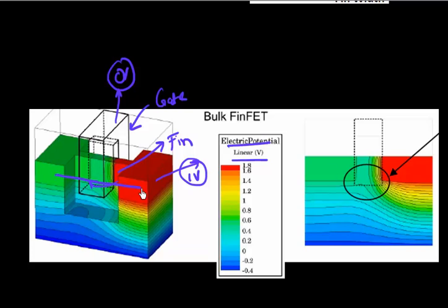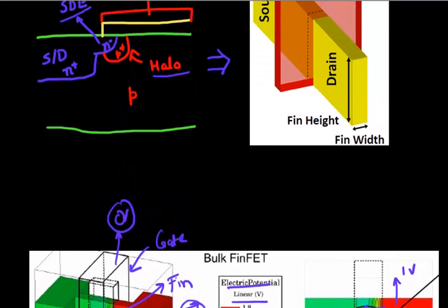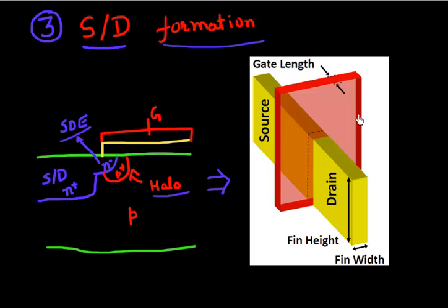If you take a cross section along this direction, which is shown here, your drain potential is pretty much contained in this drain region, and it does not penetrate through your fin to your source. So you get a much better gate control. The point I want to repeat is that since you have this much better gate control, it helps your implant design a little bit.